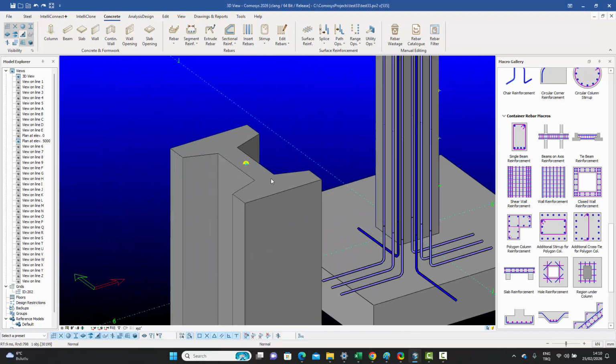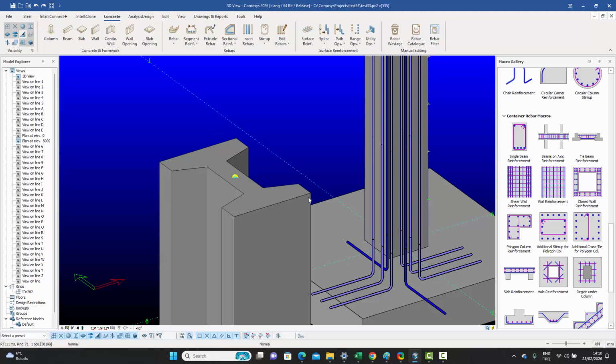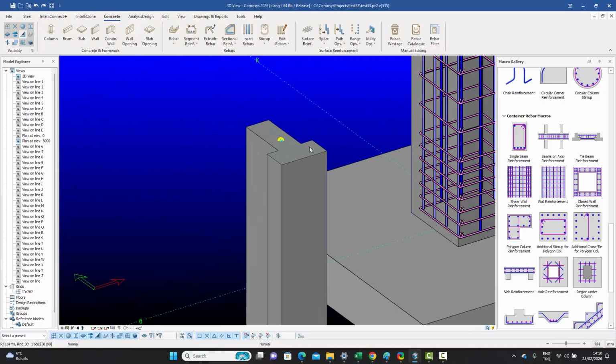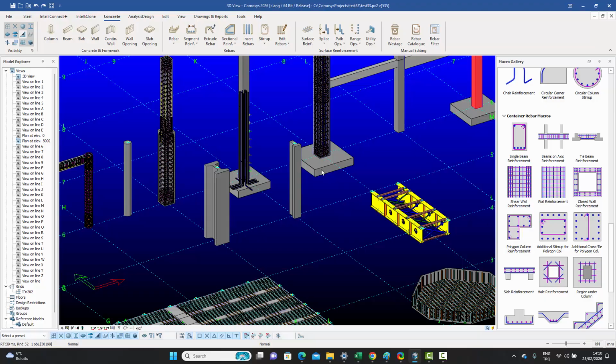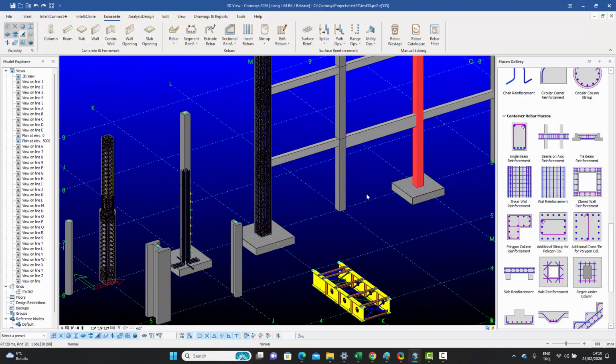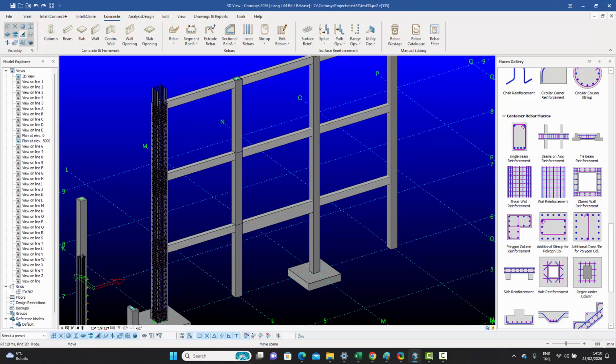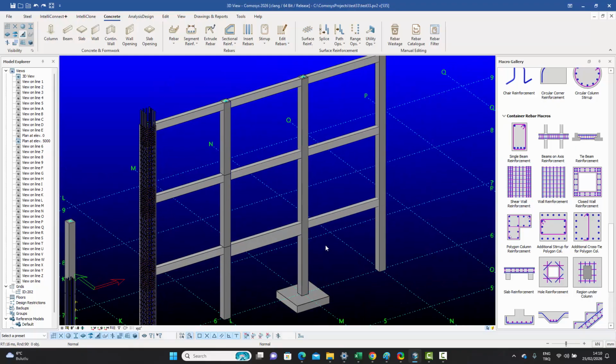for, for example, even something like this, you can put your longitudinal rebars all along the sides, and make sure that if you want more on this side, you use the parameters which I just showed you, or a T column or an L column or anything like that. The polygon column will basically work for all those cases. So now let's move on to adding stirrups.